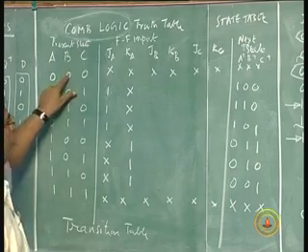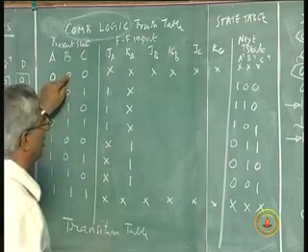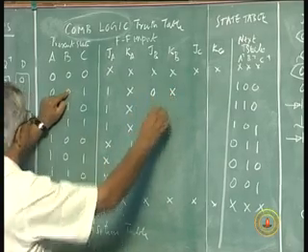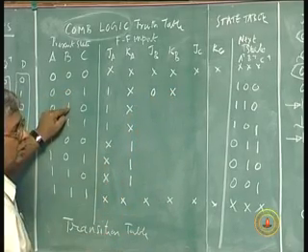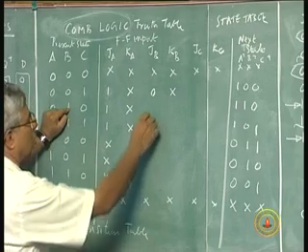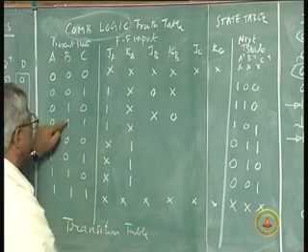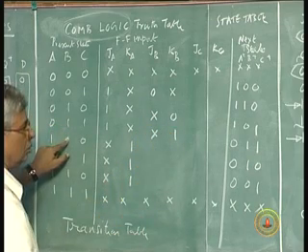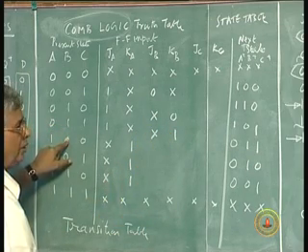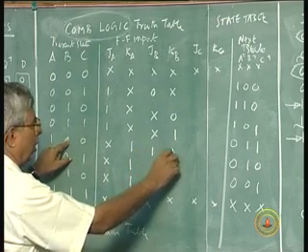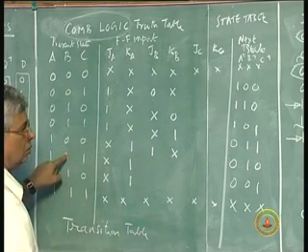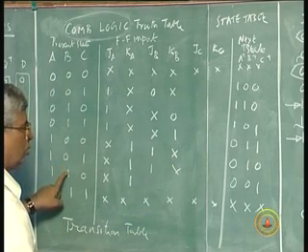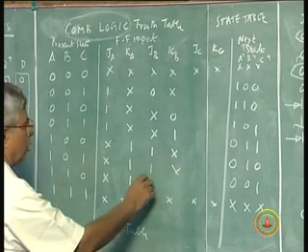JBKB, you look at the B value with present state and B value in next state. 0, next state 0, 0 to 0 is 0, do not care. 1 to 1 is do not care 0. 1 to 0 is do not care 1. 0 to 1, 1 do not care. 0 to 1, 1 do not care. 1 to 0, do not care 1.